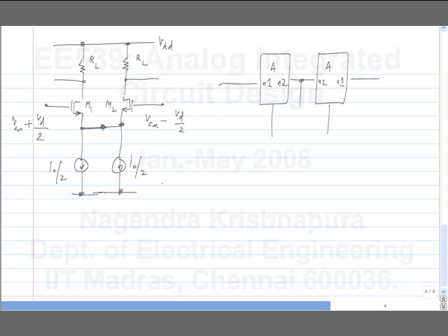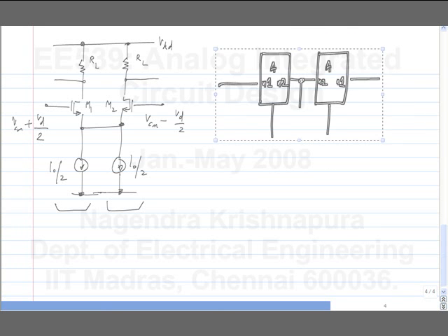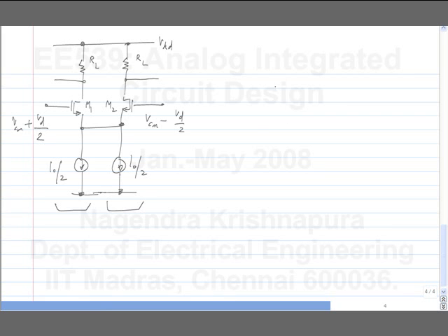Now you can clearly see that this part of the circuit and this are identical. The sources happen to be connected, and the drains are not connected. Now, you can, of course, keep every transistor and every component in the circuit and analyze the circuit. You will get the right answer. But there is a simplification that you can make. So let me consider two identical halves.